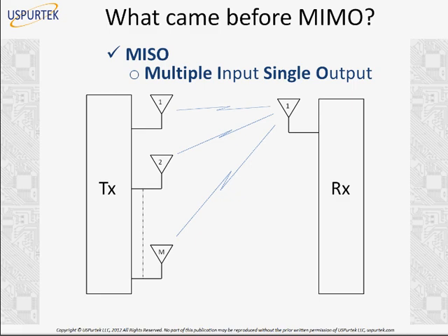So there you use a MISO system. You have multiple antennas on the transmit side. On a cell tower, you could have as many antennas as you want, basically. Okay, you have more space and more carrying capacity over there. Now this configuration too has benefits, because now you have 3 same data streams transmitted over 3 RF channels. If you lose one, you still have the second one available, or if you lose the second one, you still have the third one available, even on a single antenna. Plus, if all of them are available, you could transmit more data. You can multiply your throughput.